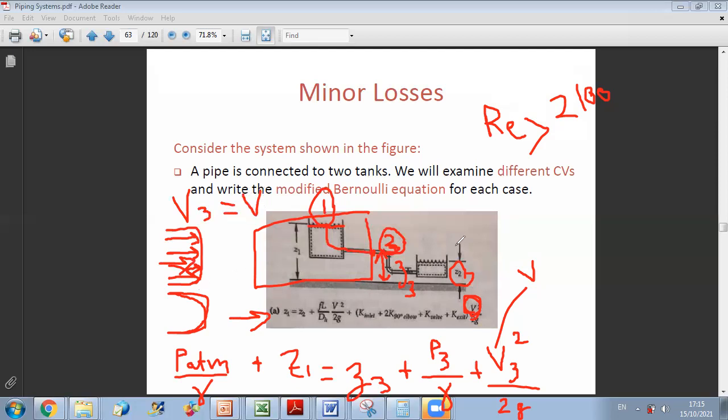While if you got a Reynolds smaller than 2100, then it's a laminar flow, and you can use formulas we developed together for the case of parabolic flow profile. So you have a relation between Vmax and a function of the average velocity V, okay?